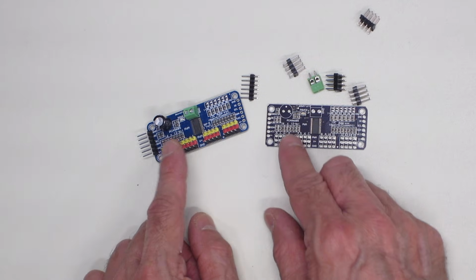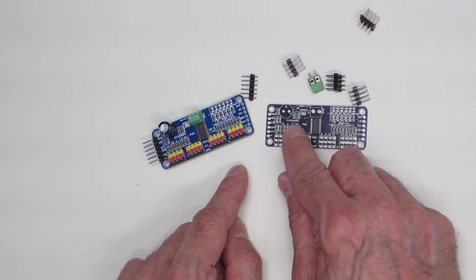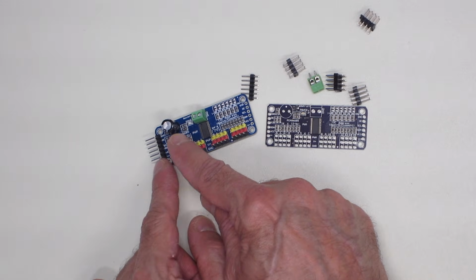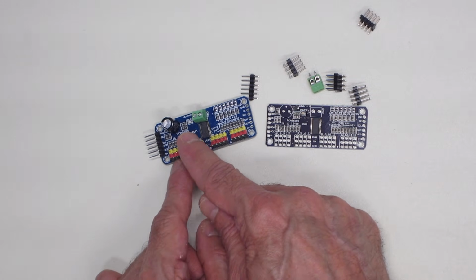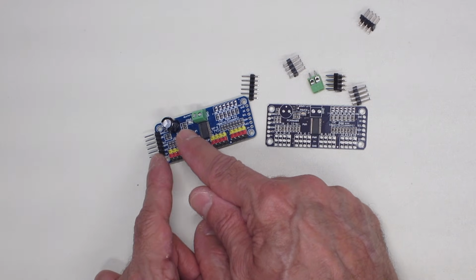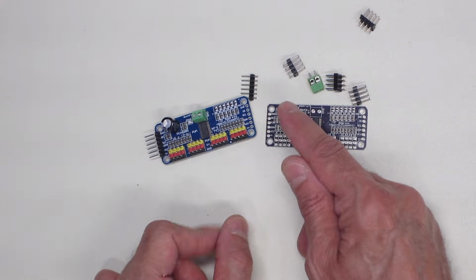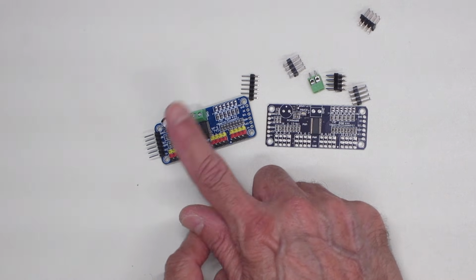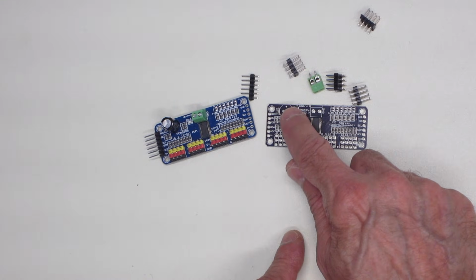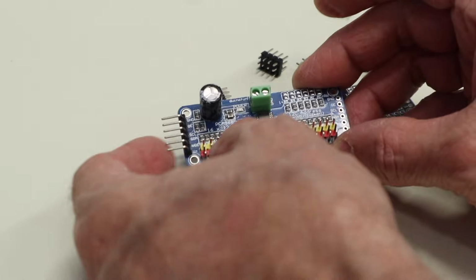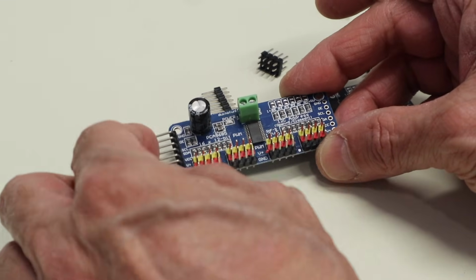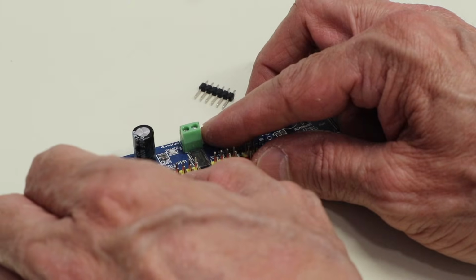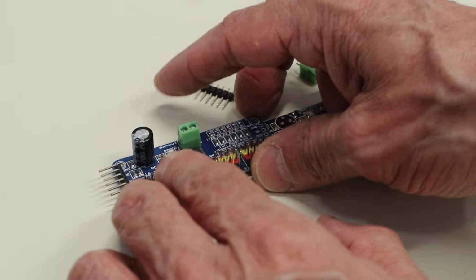The capacitor is used sort of as a current sink for the motors, and it's a good idea to have that in. If your motors are chattering, this can sometimes fix the problem, although that's not the only reason servo motors will chatter. It also is good if you have a sudden need for a lot of torque. This can hold a lot of energy, and this has a 1000 microfarad capacitor already installed in it, and there's room for it on this board as well. But the main connections, as I said, are repeated on both sides, and so the I2C and the power connections, etc. And this terminal over here is where you would attach the power for your servo motors.